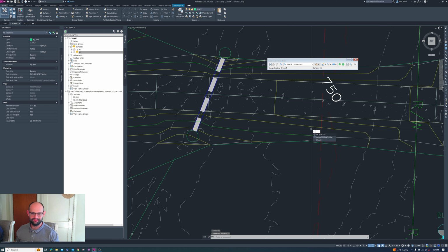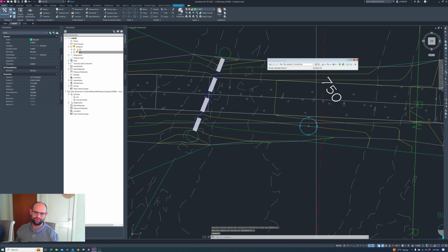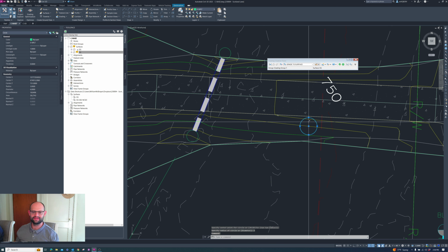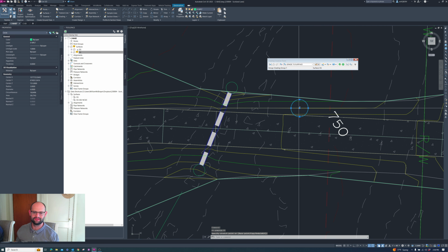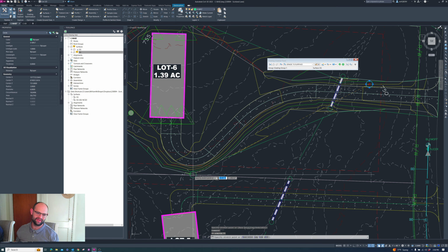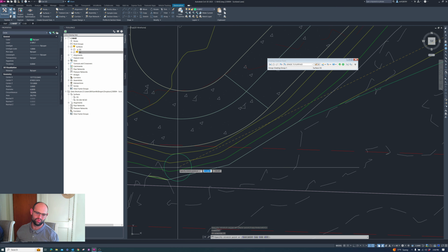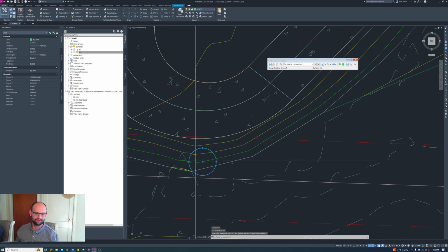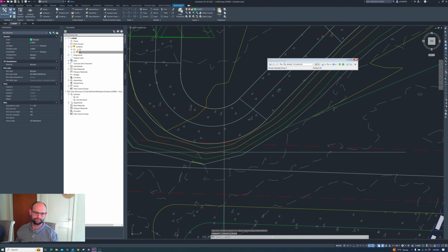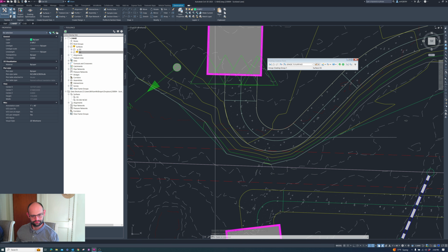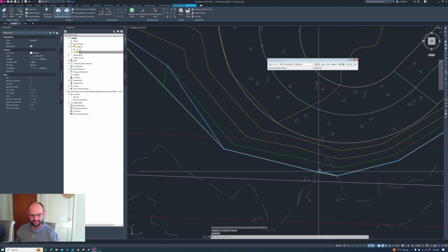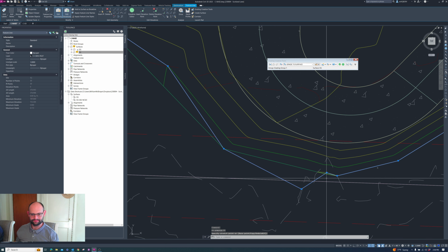Before I generate the boundary, I'm going to check some of our slopes here. So I drew a 3-foot radius circle. Cutting across some of those contours. That means I'm a little bit steep there. So we're going to pull those out a bit. More so over here. Over here is fine. So let's move these vertexes out.